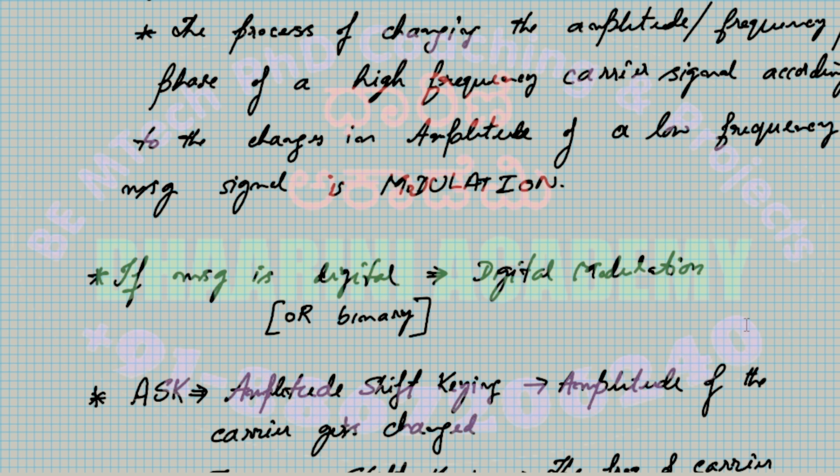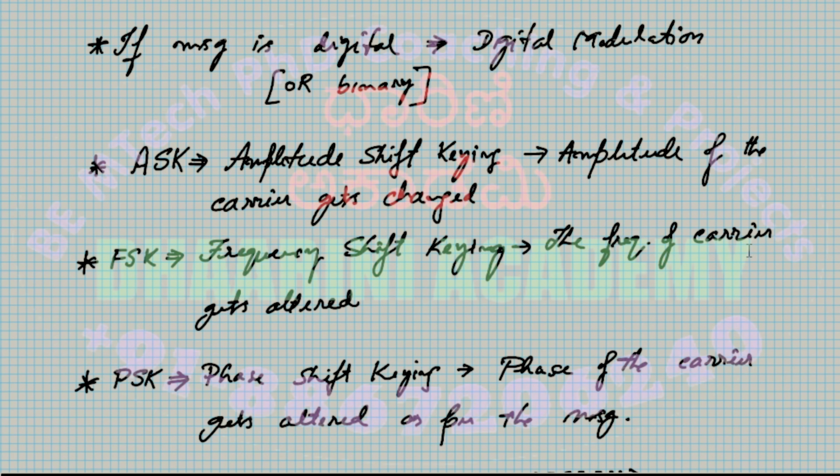But because this is digital modulation, the message signal is in digital form. Digital in the sense of levels, like binary means two levels, or any other M-ary means any other number of levels. So that's what is assumed here. So the input will be a square wave, containing the various levels. Only that is a change compared to our proper analog modulation. So the input message is digital, normally represented in binary form.